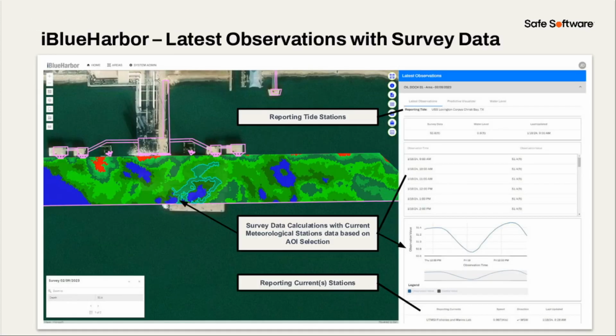From our latest observation tool, as Chad mentioned, we use a weighted algorithm within FME that goes out and finds your tide station data. It's actually a polling model, so it's constantly going every 6 minutes to pull data from tide stations. Then we serve it up within the tool and base it against your survey data, along with your 2 hour, 4 hour, 6 hour, all the way up to 12-hour observations. So we can match that against your survey data.